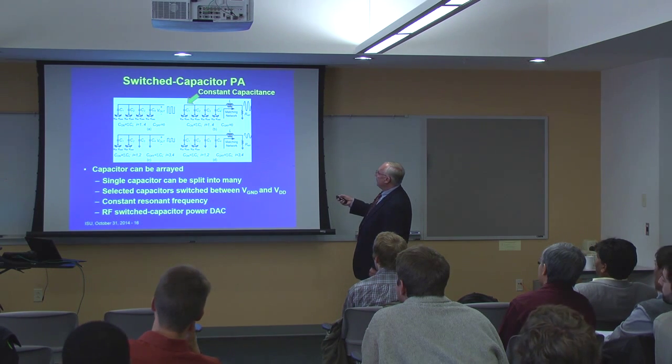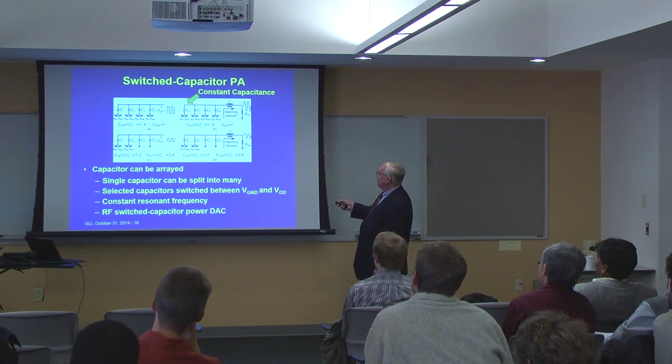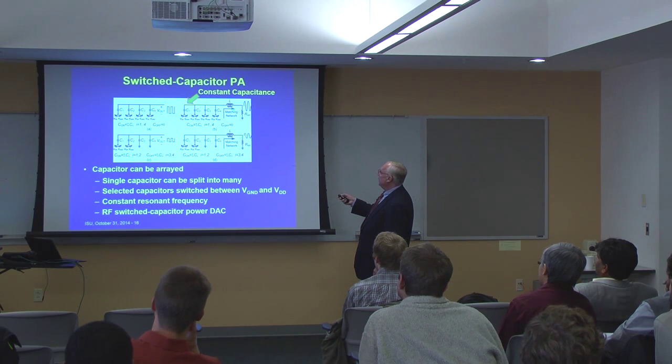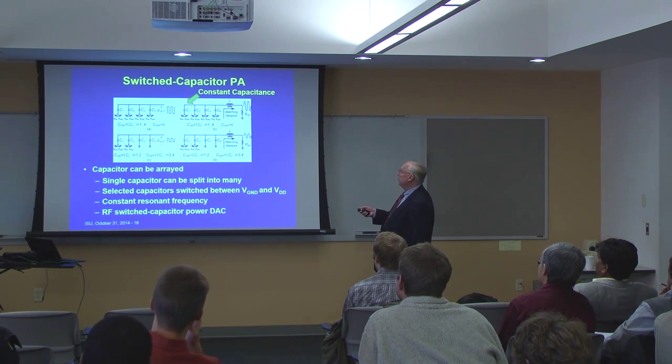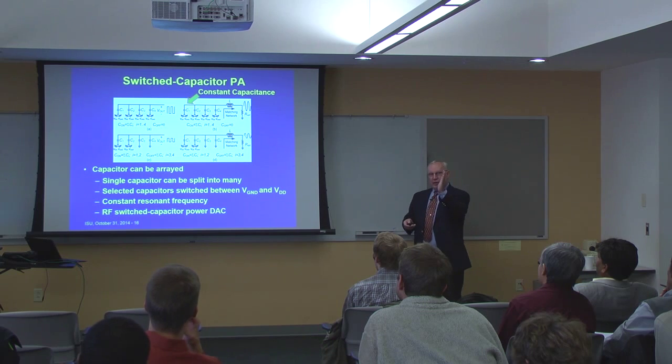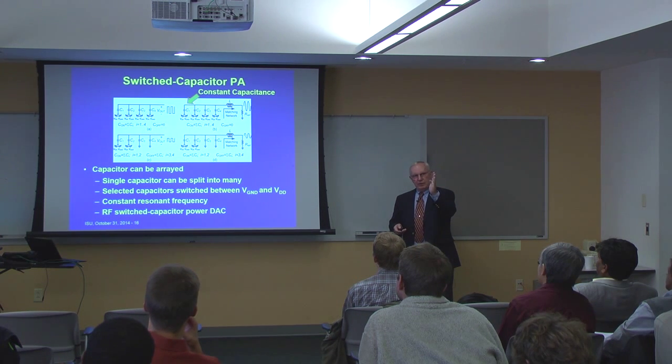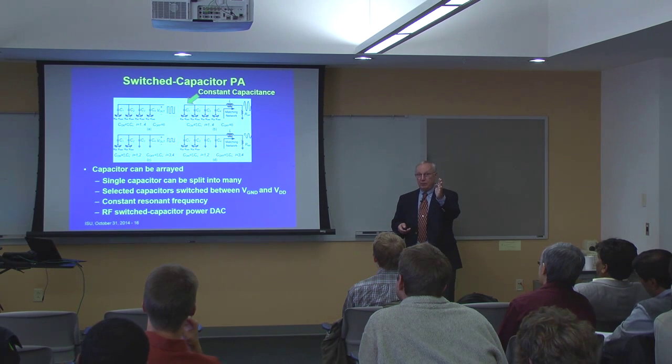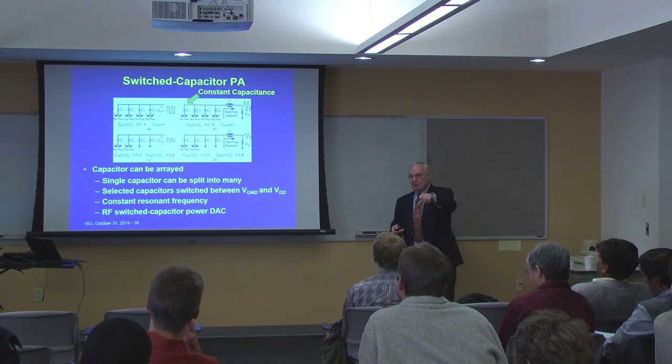So what's the rest of this? Well, this is capacitors providing the amplitude information. This is an L and C for frequency tuning, and this is your load resistance out here. If you're going to tune your radio to a frequency, what do you need to do? You need to specify, remember, omega naught equals 1 over square root of L times C. I see some students tending to remember that.